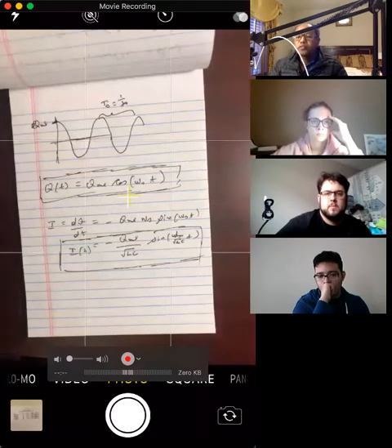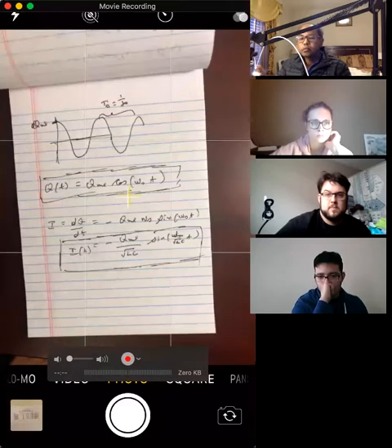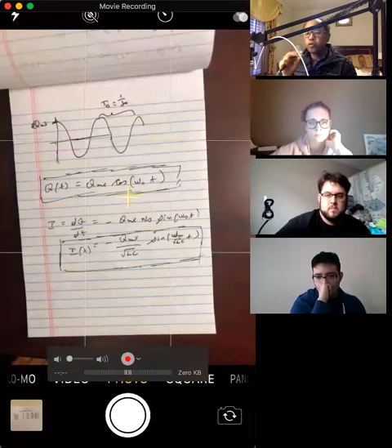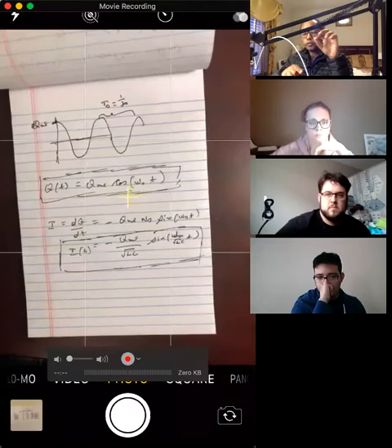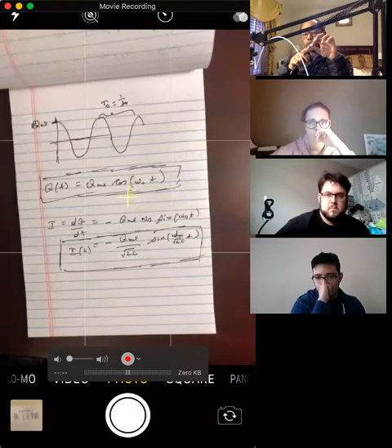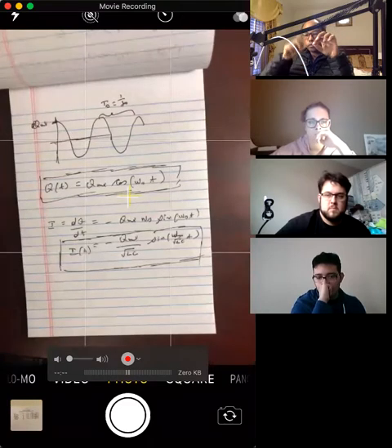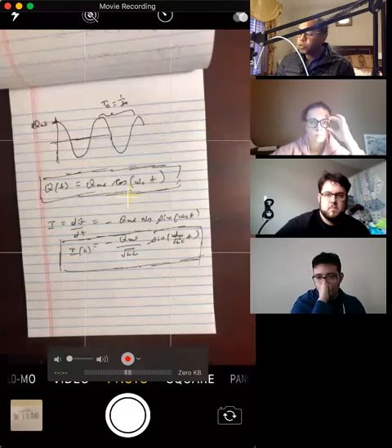So now you see this circuit will never stop. You see, cosine never stops. The charge in the capacitor changes from positive to negative forever. If you've got a spring, you let it go, what happens? Unless there is friction, it goes forever. That's what's happening over here. The charge will start from maximum, go to negative, go up, down. It never stops, just like a spring. There's no friction. So that's what's happening over here.